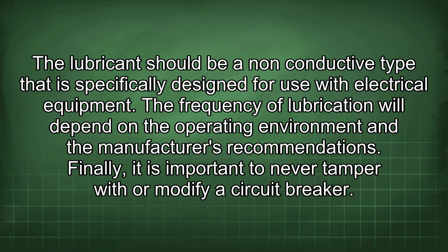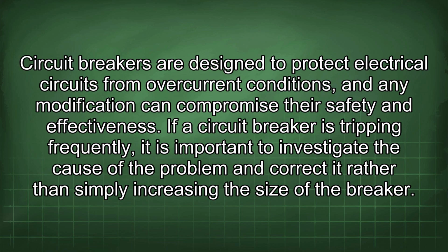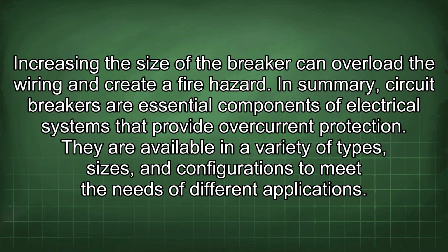Finally, it is important to never tamper with or modify a circuit breaker. Circuit breakers are designed to protect electrical circuits from overcurrent conditions, and any modification can compromise their safety and effectiveness. If a circuit breaker is tripping frequently, it is important to investigate the cause of the problem and correct it rather than simply increasing the size of the breaker. Increasing the size of the breaker can overload the wiring and create a fire hazard.